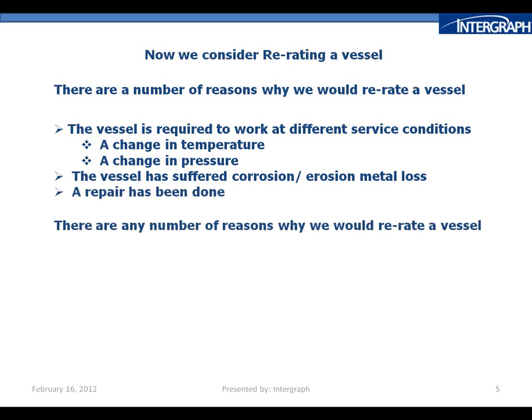We know if we leave a piece of iron out in the rain, it will rust. Obviously, the products of corrosion, which is really an oxide, reduces the thickness of the metal. And there may be products inside a vessel which will cause corrosion to occur, and we would get a vessel that actually gets thinner over time.